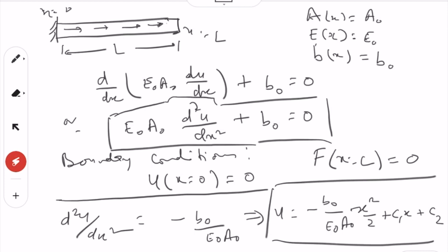The displacement here and here will not be much different. If you look at this point, there is no force at the end, and the slope should be 0, du over dx should be 0 here. So it should have something like this type of shape, right. No force, so our diagram should go something like this.